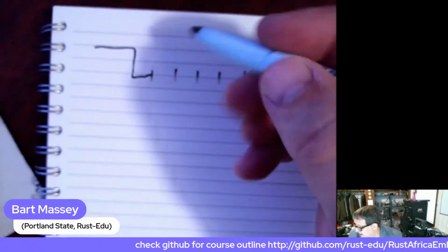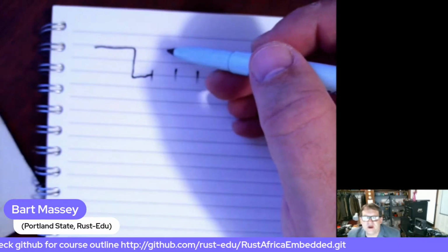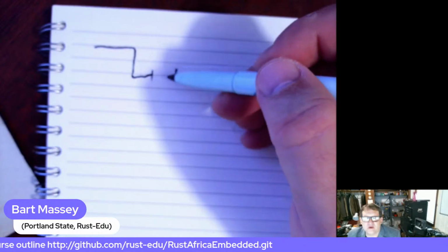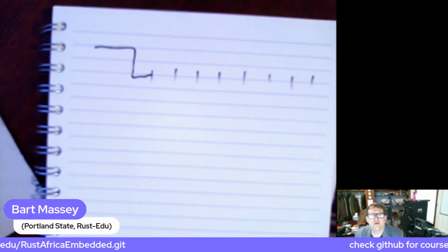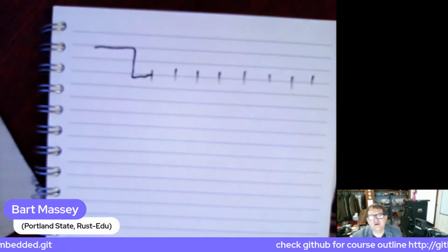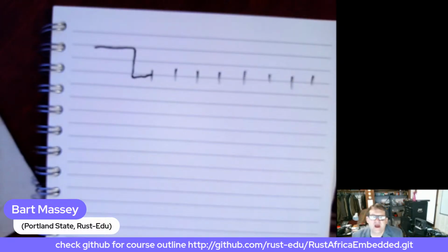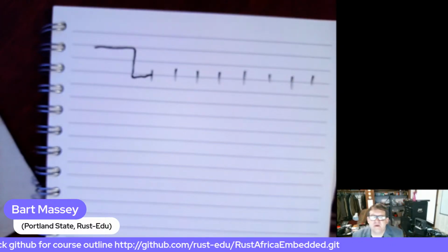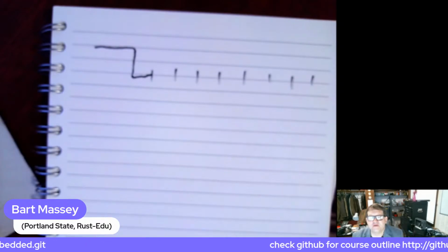But anyway, the wire will be either high if it's supposed to be a 1 bit or low if it's supposed to be a 0 bit, or maybe the other way around. I can never remember. Anyway, the point is that we just send 1 bit at a time of an 8-bit byte out the wire. And when we're done, we also delay for a little bit, another bit time, the stop bit time, set high, and then we're ready to send another byte if we want to.